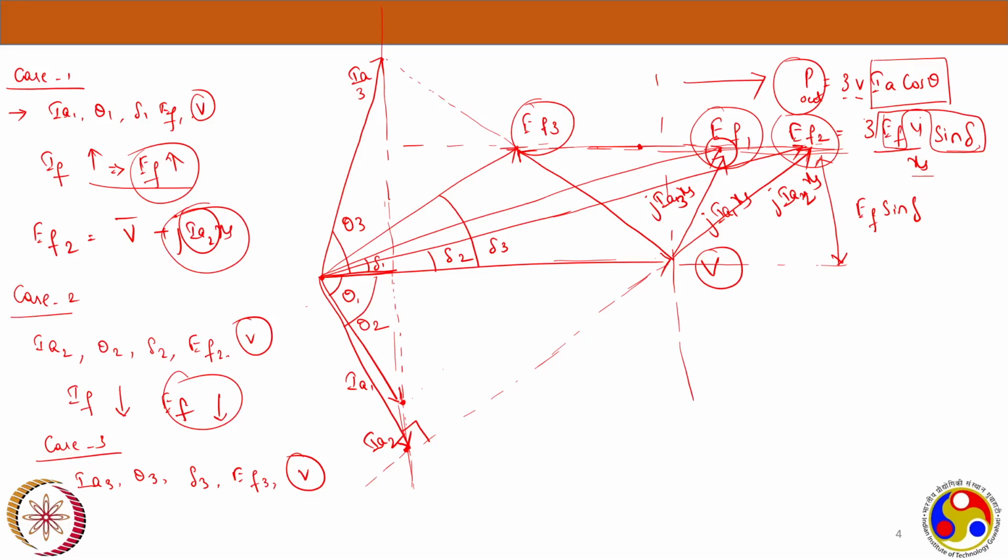Therefore, for a synchronous generator, if you under-excite it, if you provide that generator an under-excited operation, your power factor can become a leading power factor. Previously we were over-exciting it and my power factor became lagging. So you now understand, right?